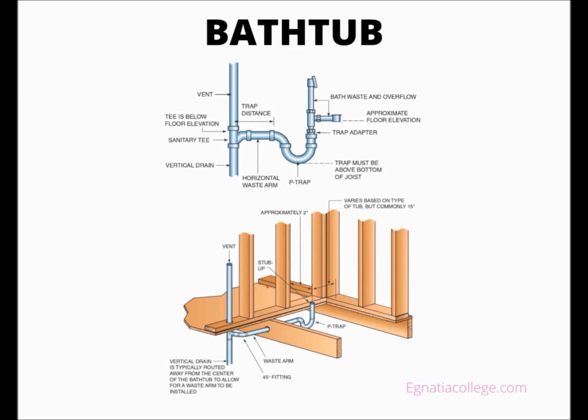Some BWO designs have a dual connection option. A plumber can connect a dual option BWO to the P-trap using a trap adapter or a female adapter. Plastic female adapters should not receive metal male threads, because the female adapter could split.